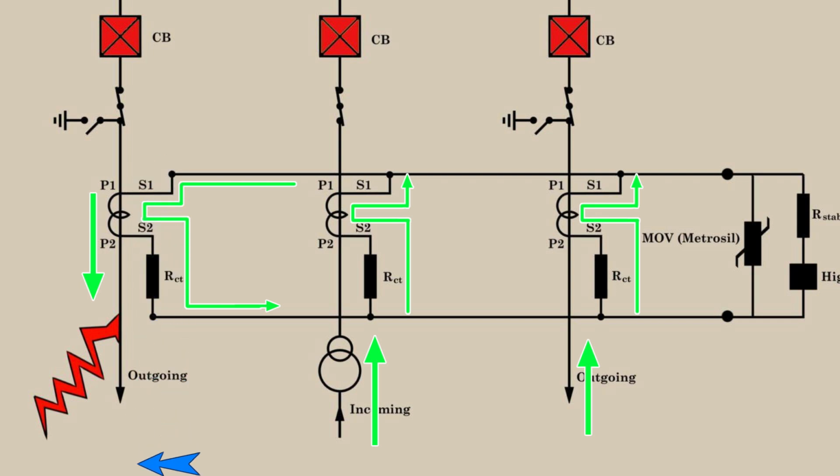Therefore, if we consider that point, then we will see the fault current is leaving out from that point and the contribution current to the fault current is entering into that point from these two feeders, the incoming feeder and the second outgoing feeder. So as a result, obviously, this fault current, which means the secondary replica of the fault current, is nothing but the summation of the secondary replica of this current and that current.